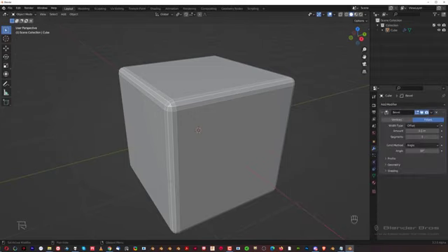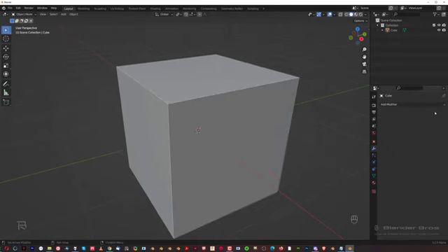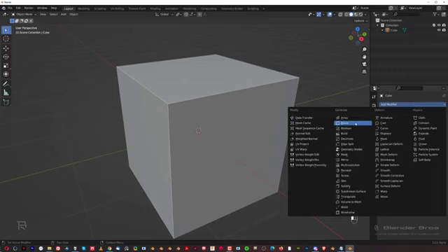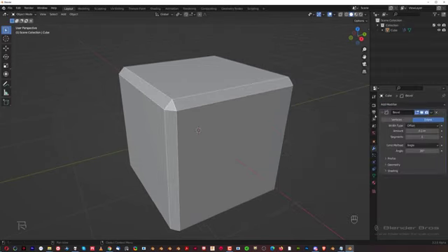And there you go. So we can collapse it here. We can also apply that, which in the case of bevels you should rarely do, or at least think if you really need to apply it. Or you can remove it here by pressing that X. The nature of modifiers is that they're live, meaning if I click on this icon here, which is visibility in viewport, I can turn off this effect.